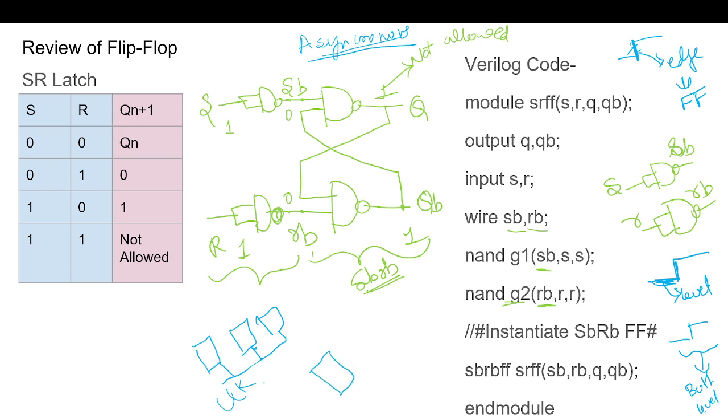But if it is asynchronous, the output of one may act as the input to another, and I will have one clock. So this kind of circuit we will call asynchronous. As of now, this is just one latch. How it is operated, based on that only we can say whether it is asynchronous or synchronous. Actually, in the assignment, we got one question related to that. It's the same diagram we need to build, and they are asking whether it is a synchronous latch or asynchronous latch.